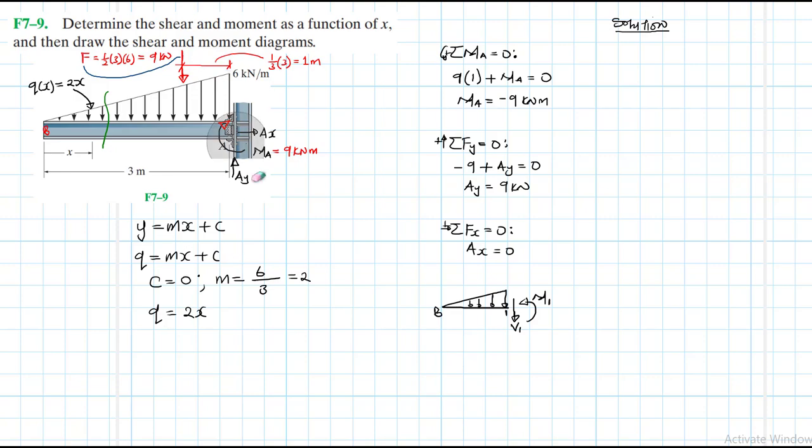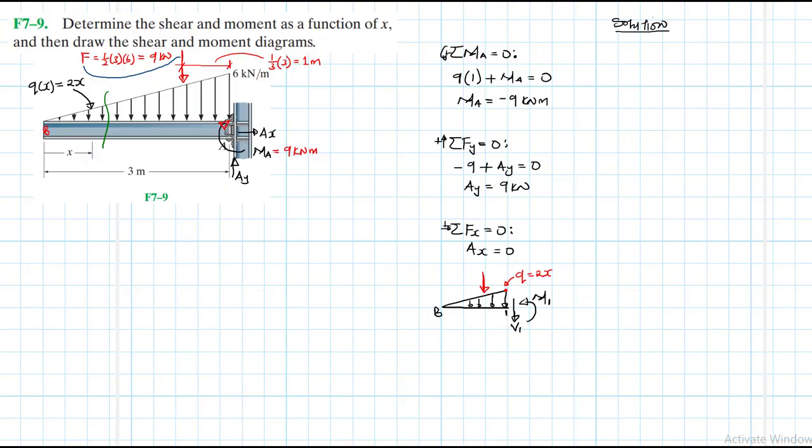All right. So our q, it is this point here. That is our q, which is equal to 2x. Then we are going to have an equivalent force. An equivalent force we are calling F, and it will be at the position. What position is that? That position is 1/3 of x, because this whole length for this small segment of the beam that we've cut is x.